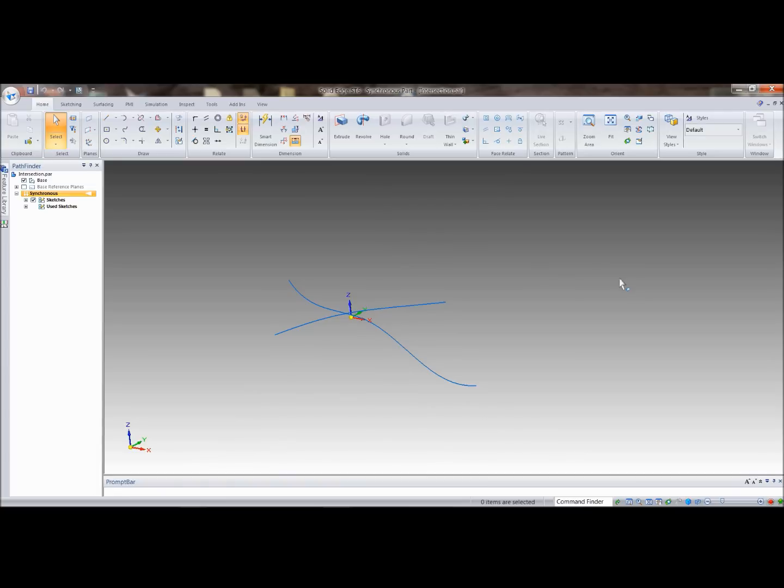ST6 gives us some new surfacing tools, some enhancements to the surfacing capability. One being the ability to intersect surfaces with each other and trim based on selections from the user as to what you want to trim. And this really streamlines the trimming capability. You've always had that ability in Solid Edge, but now you've got the ability to trim and be specific about how you're trimming things.